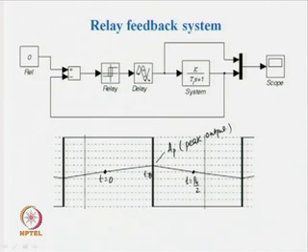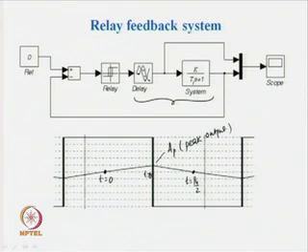So, whenever a first order plus delay system is subjected to a relay test, the typical output we obtain from the test is of this form, and this is the x axis. Whereas, during the positive output of the signal, we find the input to the system has two parts, two piecewise constant inputs.